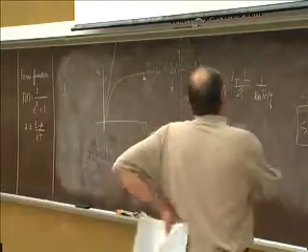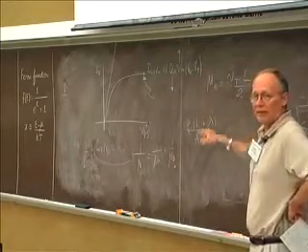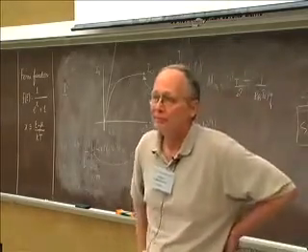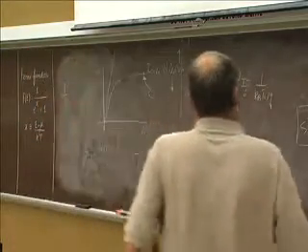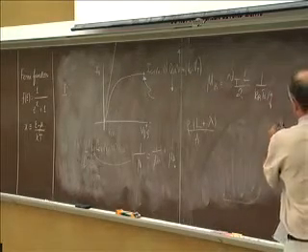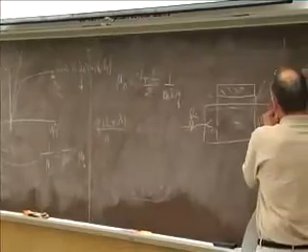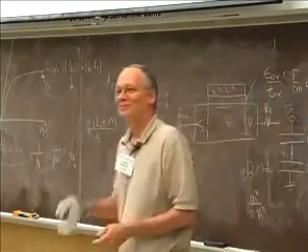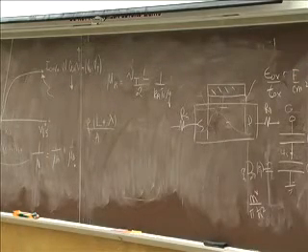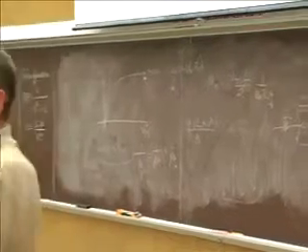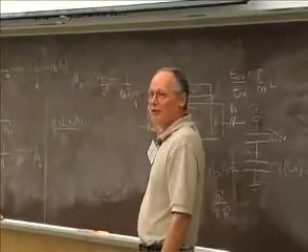Yeah, so for the ballistic case, for a given channel length, this velocity will be higher, right? But there's an issue of all the extraneous resistance, all of this parasitic source-drain resistance. These practical issues are very challenging because you're thinning everything down, making all of these parasitic resistances higher. These resistances are probably scaling in the wrong direction.